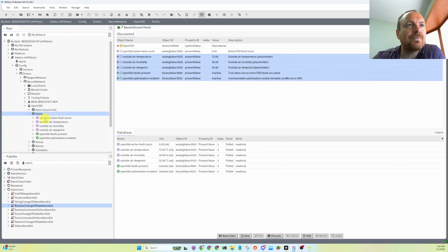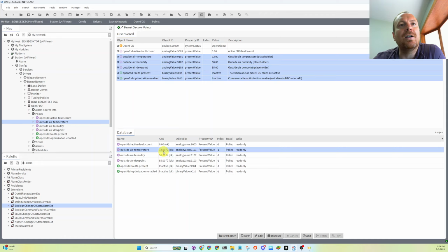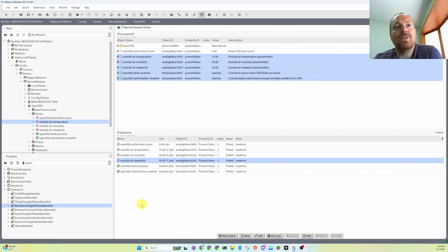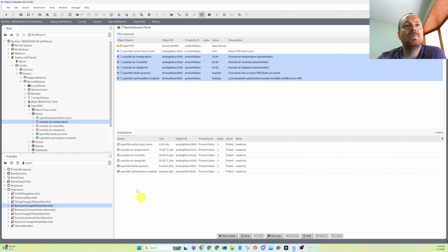And then we'll also be able to give the building automation system Open Weather Map API weather data. So this will be web weather humidity and web weather outside air dew point, which can be useful for free cooling purposes, to reduce mechanical cooling electrical consumption. There can be some more sophisticated free cooling logic that looks at outdoor dew point and dry bulb at the same time. So we'll do all that a little bit later.